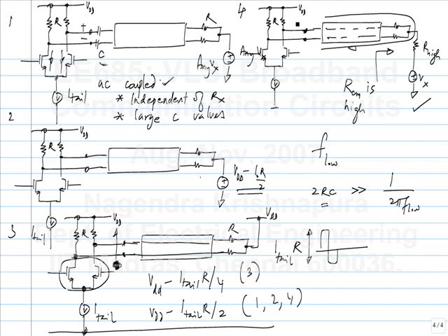You are driving the same signal in all the cases, but the common mode voltage here is the highest. So it's easiest to keep this in saturation. Let's say you wanted to increase the swing. Maybe all of 1, 2 and 4 are on the verge of triode region. You design it for a certain swing, and if you increase it any further, the transistors will go into triode region.